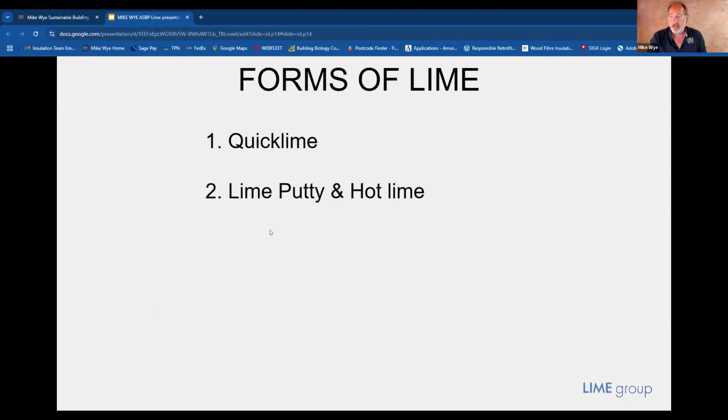Quicklime, as I mentioned, that's the reactive fired limestone product that we're starting with. We have lime putty, we have hot lime. Hot lime is an excellent and very interesting subject, and also the one of some debate in the industry itself. A hot lime mix, as I mentioned, we're making lime putty, then mixing it with sand as our primary haired and unhaired mortar products. Hot lime is a different route to a similar end, not the same, I must point out.